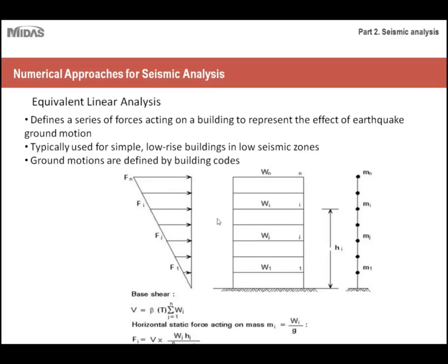For example, here you have, I don't know how many stories this is, but you have a low-rise building, and in order to create your seismic loading, you just take a force and model it as a triangular distributed load, which increases the higher you go up, because the farther away you get from your foundation, the more flexure you'll experience as you go higher up.